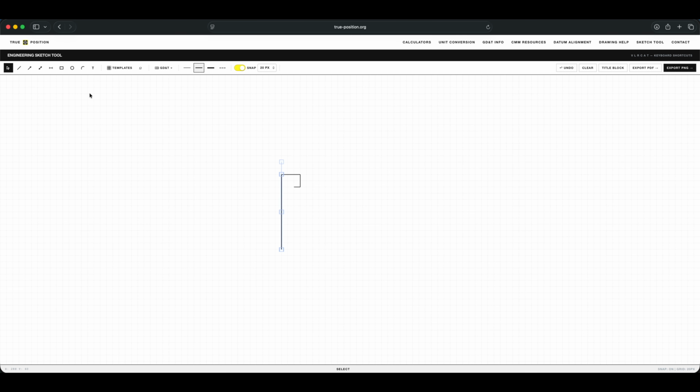Basically, it was the first time I came across a drawing that wanted to control the floor of an internal cavity with a true position. Rather than asking for a linear drop, a flatness, angularity, parallelism, etc., the designer wanted to control this surface with the true position of a plane. I had to seek advice from someone outside of our company, so I was unable to share the drawing. This tool would have been perfect for such a situation.